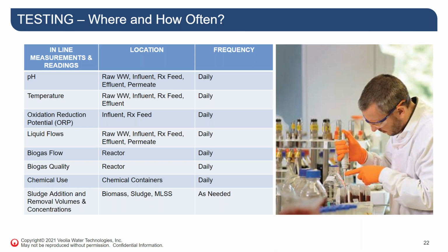What we typically do is, at each pH meter that's in line, daily we collect a sample and bring it to the lab and check it against the lab meter, which we know has been calibrated every day. And if the difference is too great between the inline reading and what we have in the lab, we'll take that probe out of the line, clean it, check it, and if necessary, calibrate it, and then put it back in. It's so important.